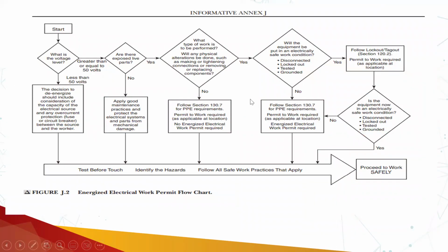Okay, I have put this here just to make one thing clear: permit to work is not equivalent to energized electrical work permit. Here they have mentioned permit to work required as applicable at location. Energized electrical work permit is different to permit to work.